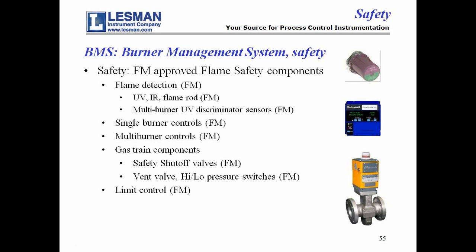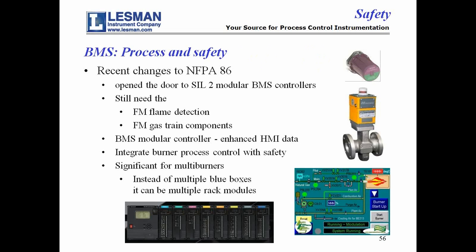Now there's been a change to NFPA 86 in the last 2 years, and it really opened the door to have SIL2 modular burner management controllers package the stuff instead of discrete components, to go to something like you see on the bottom down here with modular control. Now you still need to have flame detection. You still need to have the sensors on the gas train and the safety shutdown valve, but the logic making decisions can be done modular, and as well you can do the process stuff in these kind of boxes as well.